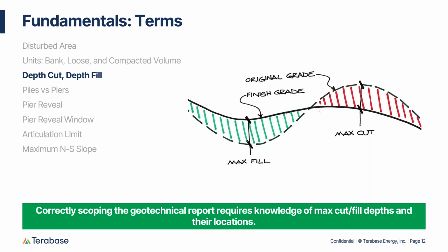Deep fill might require under drains, deep cuts might require benching. And so the message I want to drive home here is that geotechnical recommendations have ramifications for project cost. And unless you're telling the geotech where you're cutting and where you're filling and how deep those are, you're missing some potential costs there. Next slide, please.